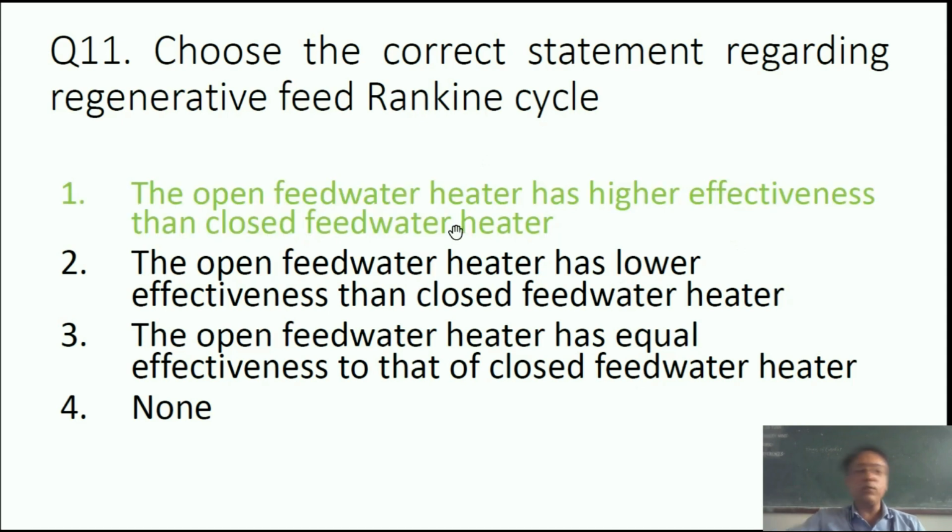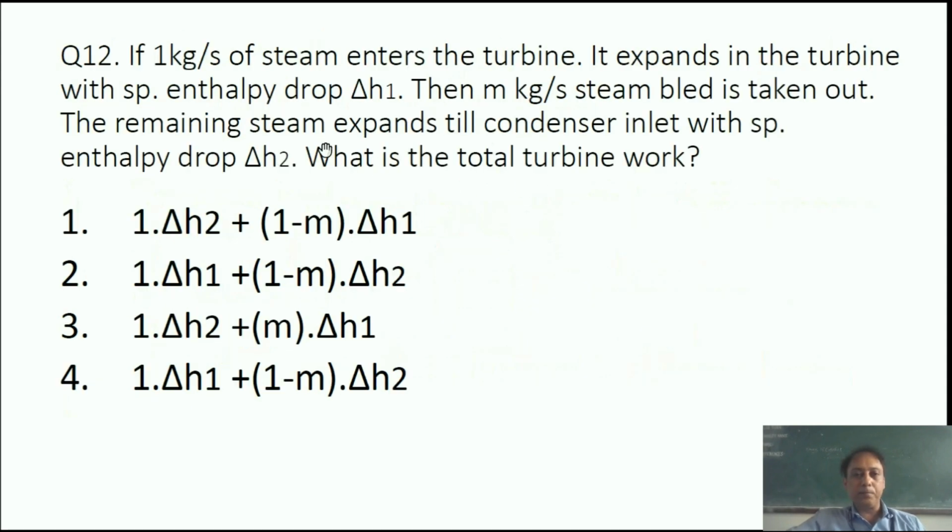Open feed water heater means what? The steam that is taken out is directly mixed with the liquid water. So in this case, the heat transfer is higher compared to that of closed feed water heater, in which the steam gives up its heat to the liquid water by heat exchanger mode. Means the steam doesn't mix up with the liquid water, just heat is transferred. So remember one thing, that open feed water heater has higher effectiveness than closed feed water heater for the case of regenerative feed Rankine cycle.